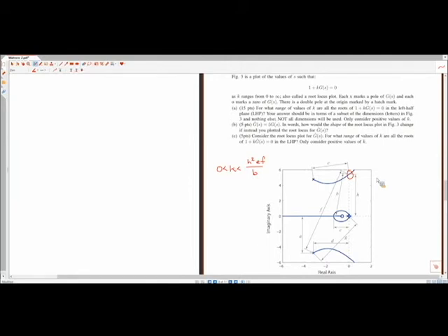So if we were to say what G of S is, or the magnitude of G of S, for Thomas's selection of S, you would say from this vector coming from the double pole, you have an H associated with the first pole at the origin, then you have two of them, so that's H squared, right? There's an F from the magnitude from the bottom pole, the other half, and there's an E from the top one. And then there's a B from the zero. So the length of the vector coming from the zero to that position is B.